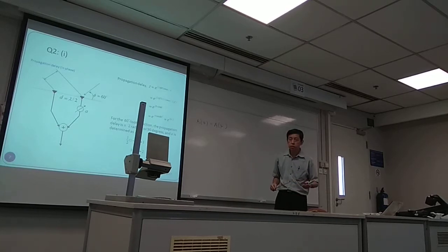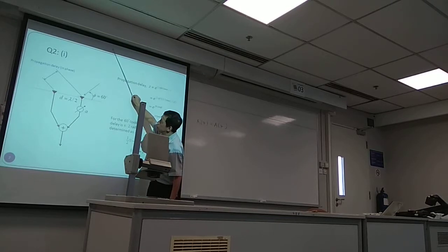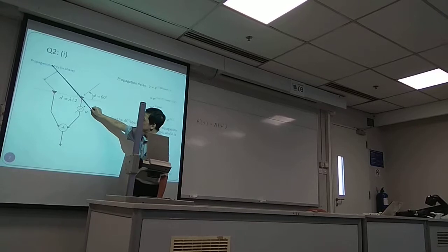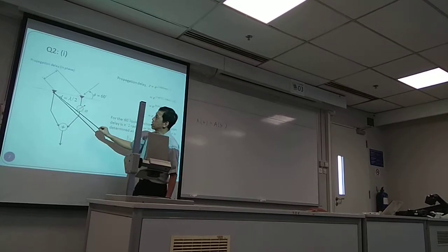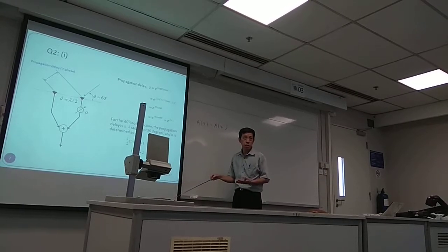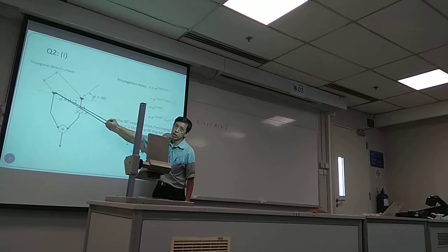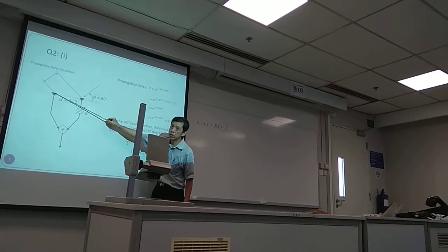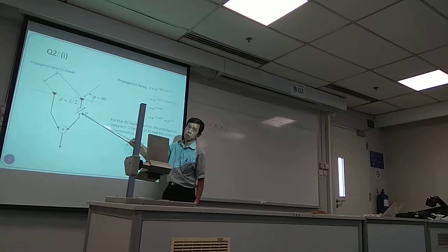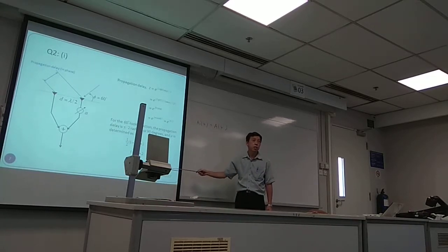Follow? So what is the physical interpretation? Signal when it is approaching from the 60 degree look direction, the subsequent element, the signal received will be 90 degree delay. Alright? So the signal here will be 90 degree ahead of the element on the left. So therefore, you need to delay the signal over here. So how many degree? Of course, minus 90 degree. You follow?